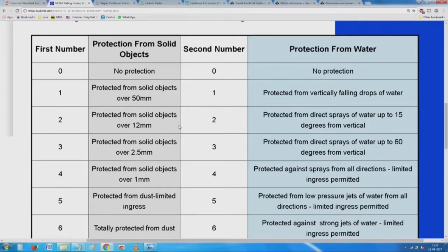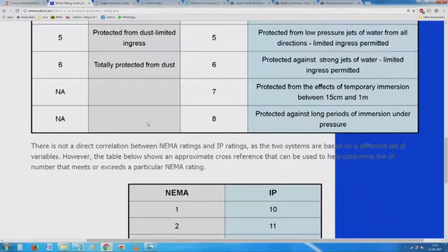open chassis equipment. Sometimes if you make a power supply and those things, if you remember in the beginning I showed you one panel building. So you have panels in which these equipments are all mounted. The outside big enclosure is fully protected. So in this case, generally IP20, IP10, all these things mean that it is a box which is generally protected. It is open, but is expected to be used one more time in another equipment. So most of the small sub-assemblies, including the PCBs you are talking about, are probably taken from here.